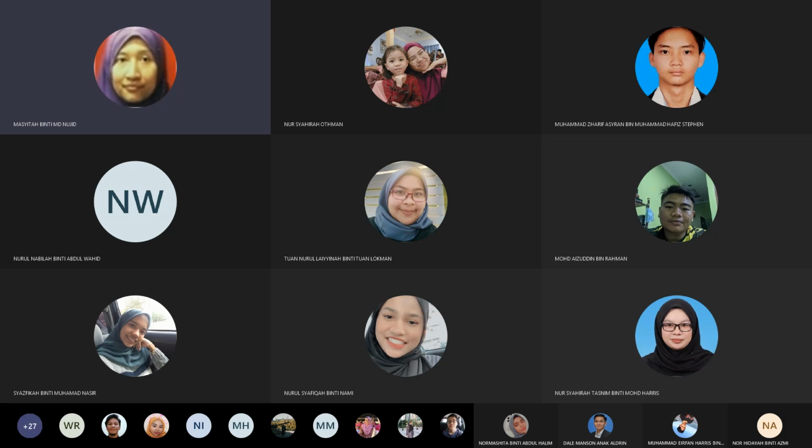Remember, in our table, the next slide shows that you have to find the B, the H1, the H2, and then the area for each slice. You have to find the weight or the volume of each slice, and then the interslice angle. Next, calculate the T, the disturbing force, and the last one is to calculate the resistance force N. The T is equal to W sine alpha and N is W cos alpha. So what is B? Again, B is considered as the width of the slice.